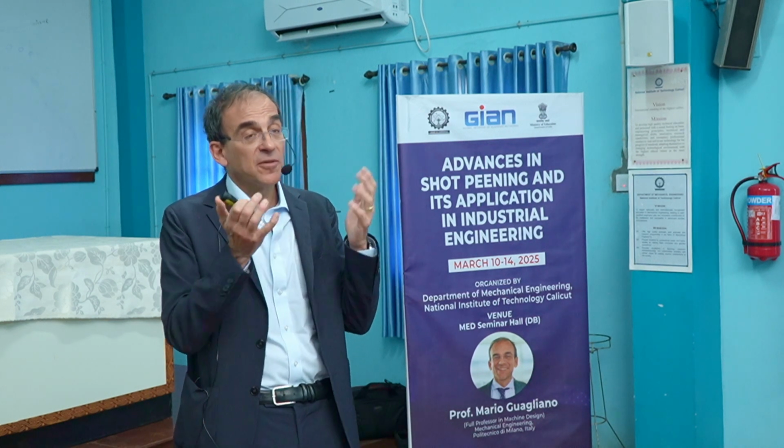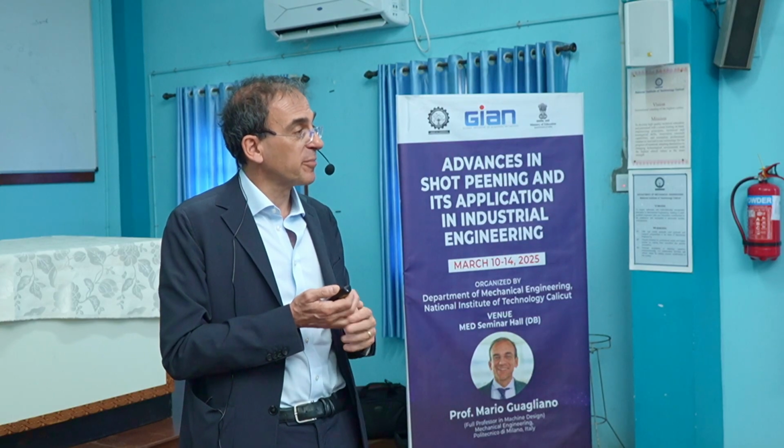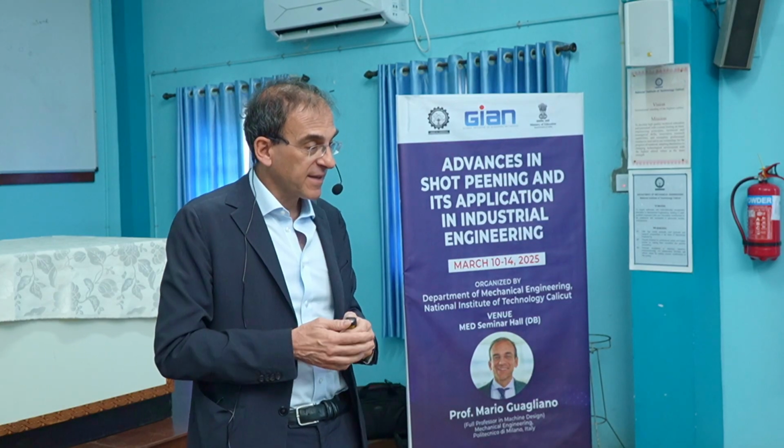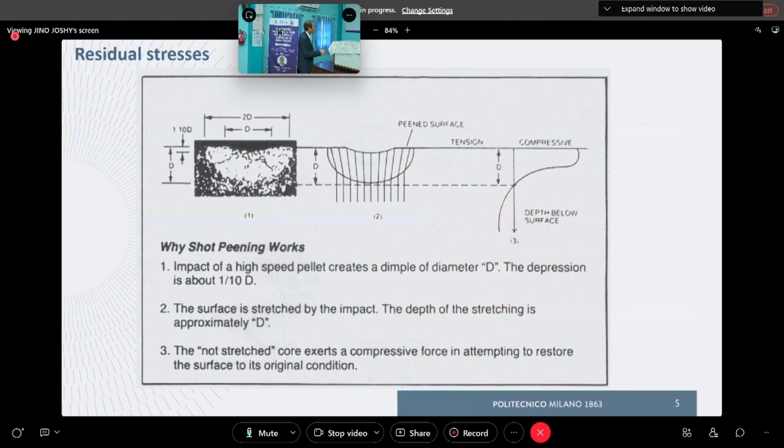Okay, and so what happens? They press over the surface layer of material, causing the generation of compressive residual stresses. This is what happens with shot peening, with a final trend that is this one, with a peak that generally is under the surface. Then the residual stress, after some depth, becomes positive, tensile, because we know they are residual stresses, they are self-balanced.